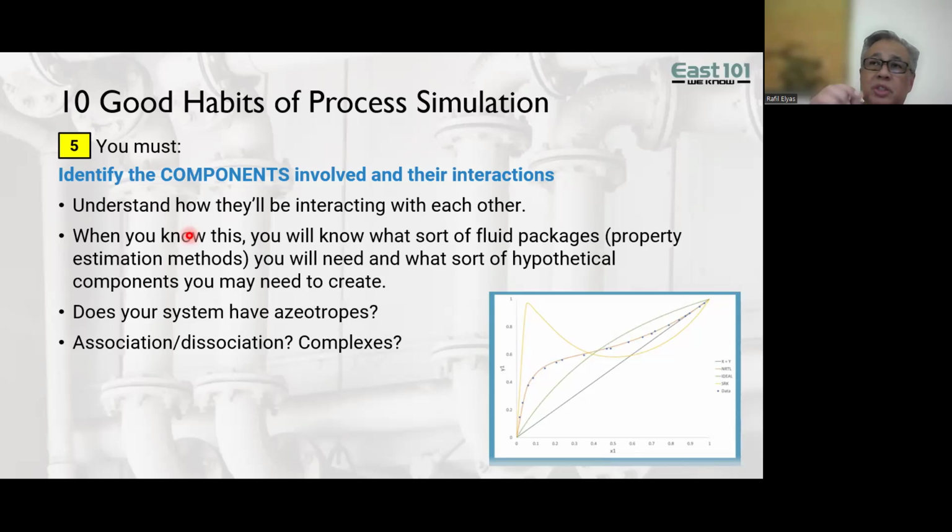But if I'm using methanol for hydrate suppression, where I've got methanol and a hydrocarbon stream, more like a gas stream, and I'm chucking in methanol when I start up a well, when the temperature comes down I get this chilly choke effect, which can result in hydrate formation or solid formation. I chuck in methanol there to prevent hydrates from forming.